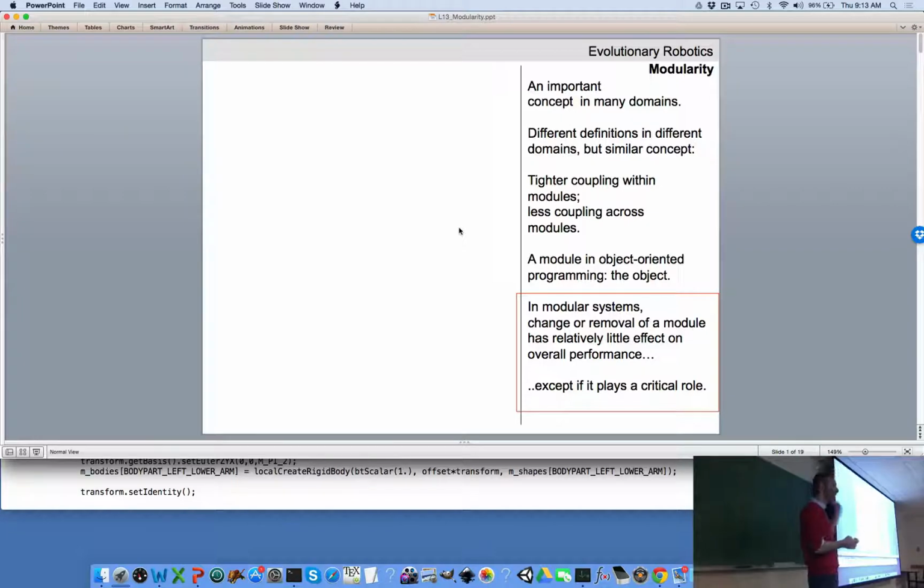So in the case of the passive dynamic walker that we just saw, they actually manually put in some modularity there, right? They kind of cheated a little bit. What was the modularity in the passive dynamic walker? The CPG versus the legs. So you had the leg module and the CPG. You had two modules, right? And they're identical modules. One neural network for the left leg, one for the right leg, and then the way in which these modules were energized was dictated by the CPG, right?